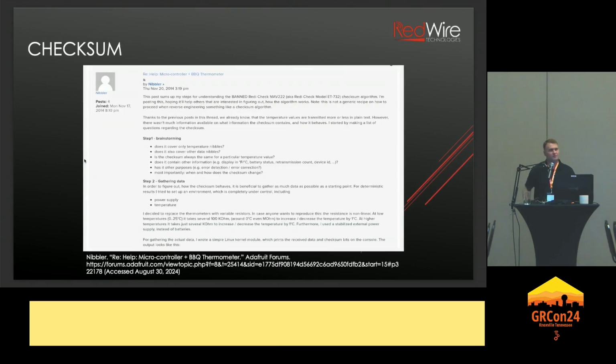Now, at this point, I was getting pretty close to the conference, so I went Googling around to see if I could find documentation, to see if anybody else has done this. I found some other people playing with the same thermometer in different projects, and on the Adafruit forums, I came across a user named Nibbler who has a great post explaining how they worked out the algorithm for this checksum. It's actually an XOR mask that changes, calculated from a linear feedback shift register, and that's applied to the data, and the result will give you a session ID, which is how the thermometer syncs to its receiver.